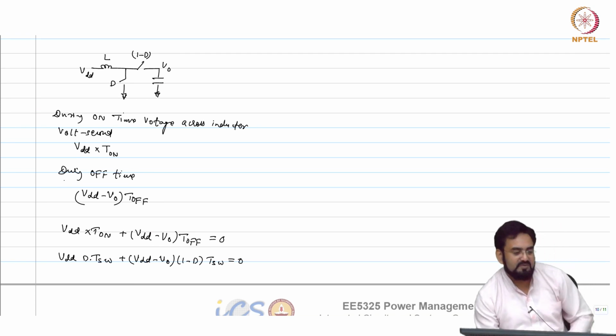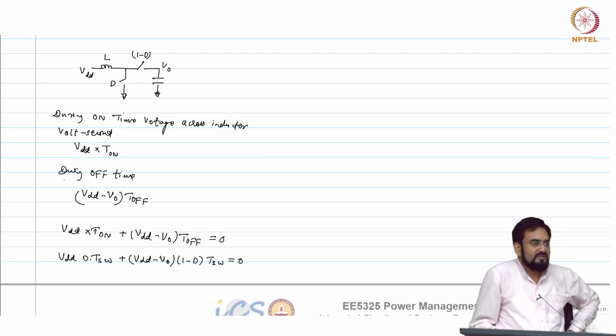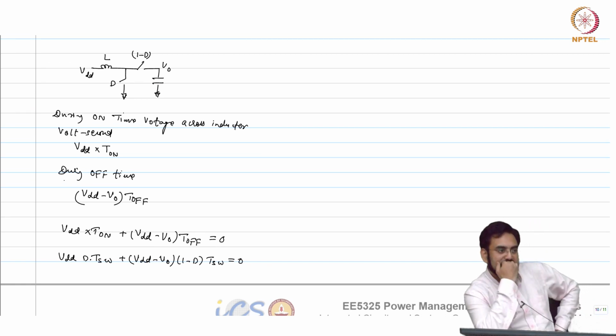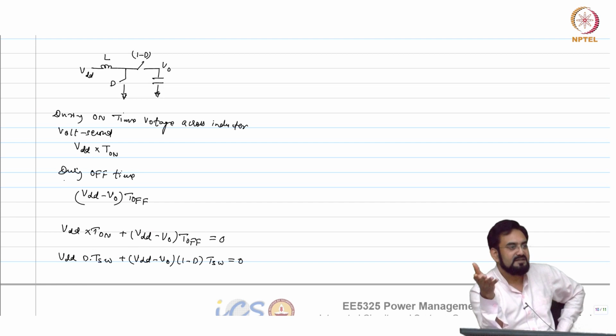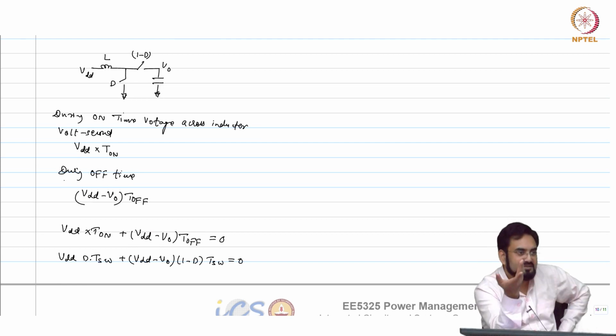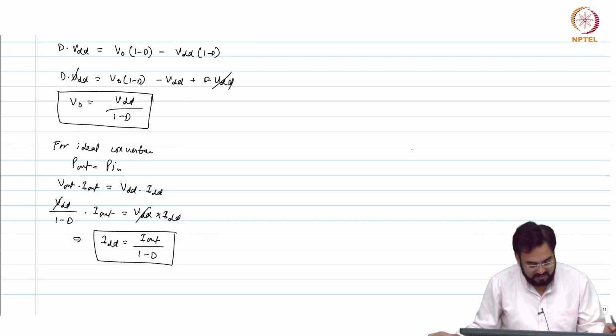Ultimately it will not benefit that much when you do it in stages. You do it in stages because we are limited by duty cycle. So, let us say I limit my duty cycle to 10% and I want 20x. That is not possible. So, in that case you do 2x and 10x, or 5x into 4x, and you get 20x.